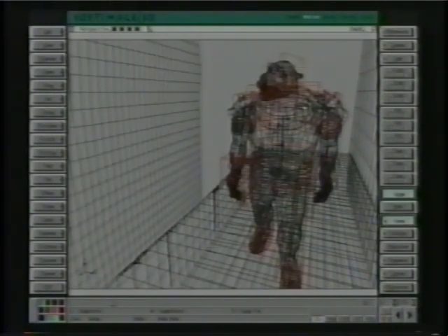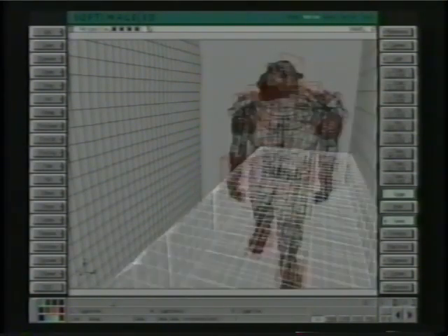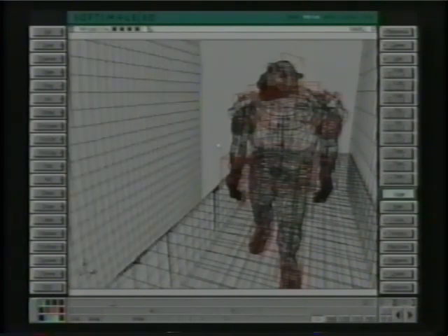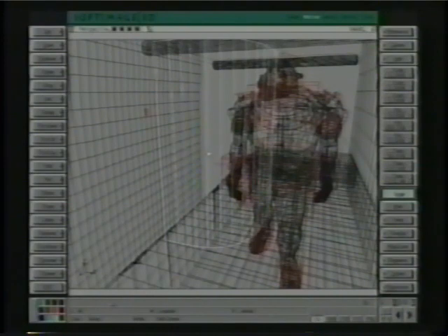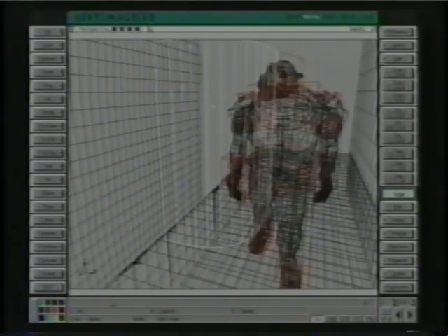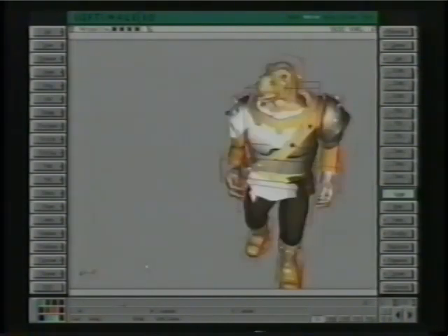So now instead of having to reselect all these items here, we had a whole bunch of things selected. Rather than unhiding all and then having to make a new selection, you can just do that with the hide ghosted and ghost hidden. And I have hotkeys that do that, so I can do it very quickly. Ghost hidden, and then toggle it, unghosted, and then hide ghosted. And that way you can pick things in and out of their visibility without having to always unhide all or go fishing through the schematic window.